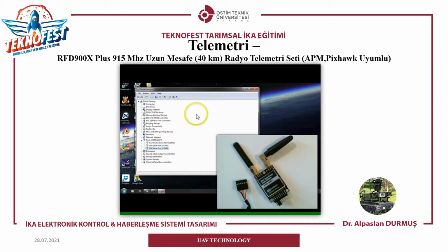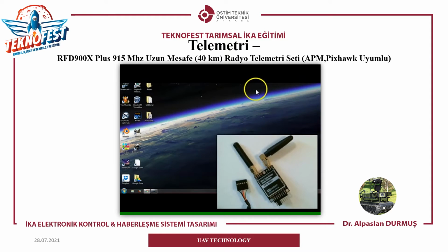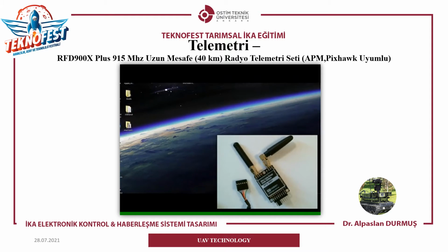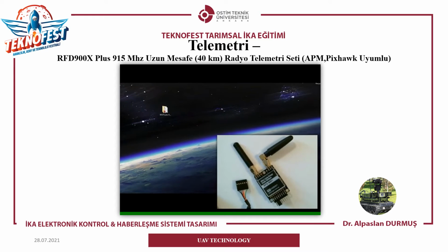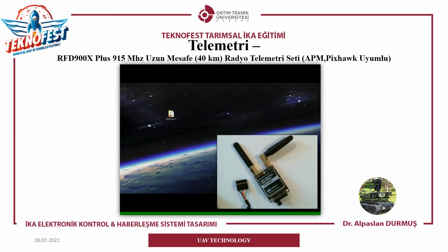Now, this number won't ever change. As long as you're using the same computer with the same FTDI cable, this COM port number will stay the same. Once you look it up once and remember it, that's the COM port you stick with. You can use other cables. You'll just have to go back into the device manager and look up to see what COM port number it was assigned.